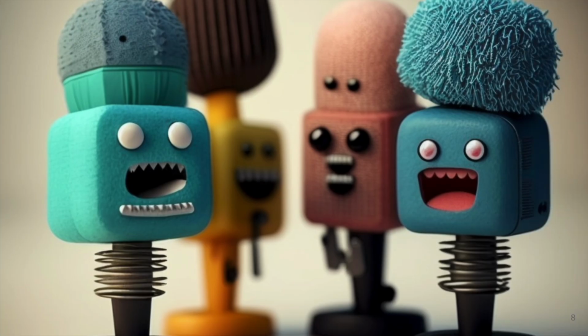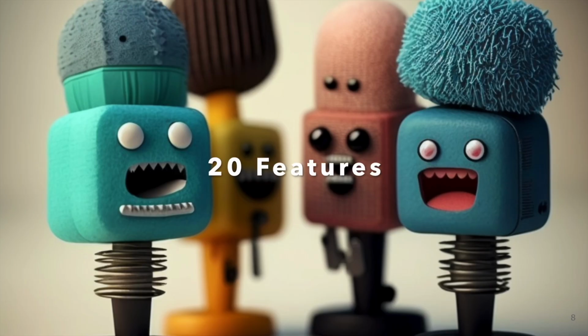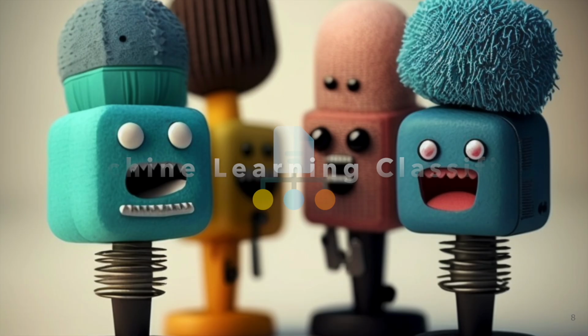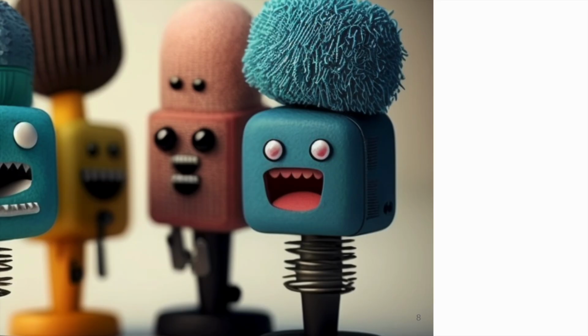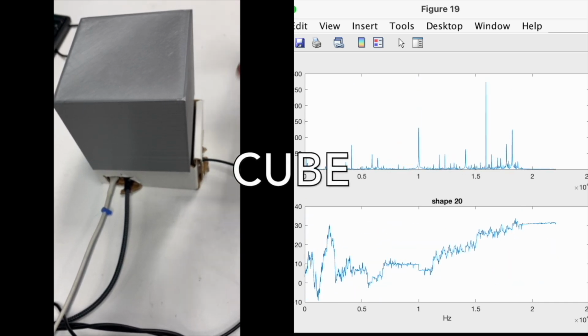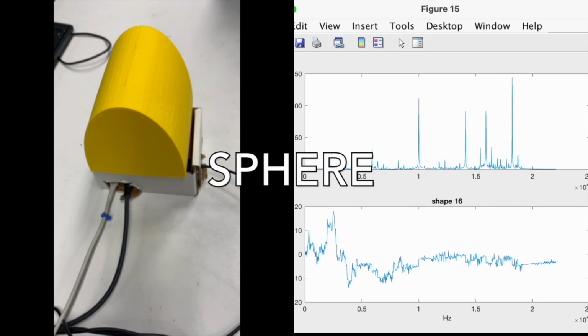Our method uses a 4-microphone square array connected to a Raspberry Pi with a central speaker emitting sound. The microphone captures audio signals reflecting off the environment, and over 20 features are extracted and fed into a machine learning classifier as training data and testing data. The features are first plugged in individually, but then they are combined to improve the algorithm performance. In this case, the setup is being used to determine which of the 3 shapes covers the microphone array.